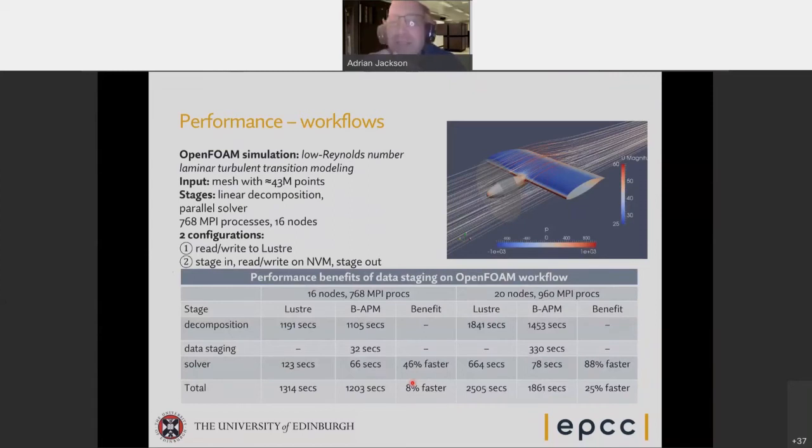for applications. And one example of something we did in the past was some OpenFOAM work, where we were looking at running OpenFOAM simulations here, either using the external Lustre file system or writing and reading all our data locally on the in-node storage and then copying it back out to the Lustre file system at the end. So in this scenario, we're still using that external file system, but it's only ever used as a store before the job starts and a store after the job finishes. And all the stuff that's happening as the job's running goes to the local storage. When your job's finished, the data gets copied away and off we go.